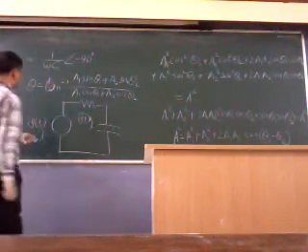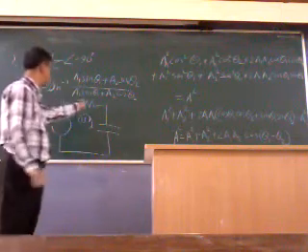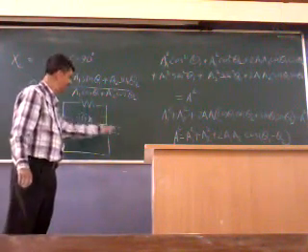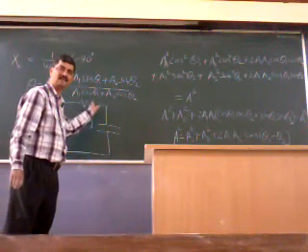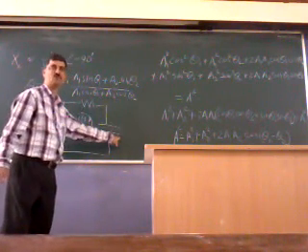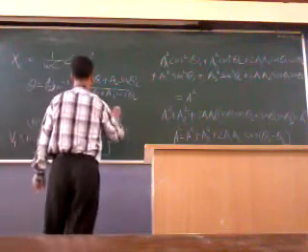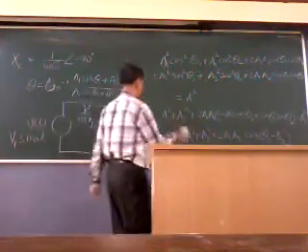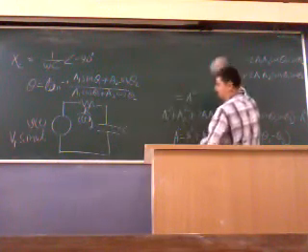So V(t) upon i(t) would be the ratio. This ratio would be impedance: R angle 0 plus 1 upon omega C angle minus 90. So this is R and this is C. So we want to add these two.